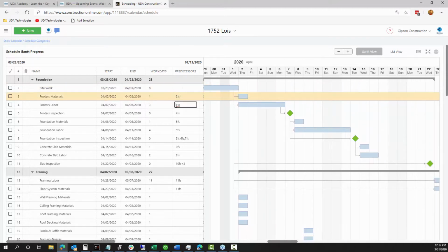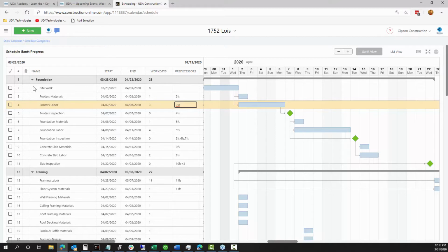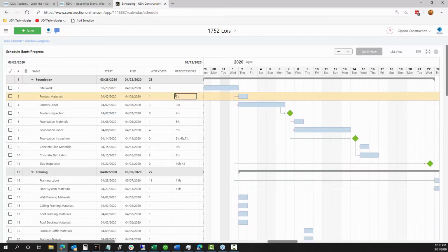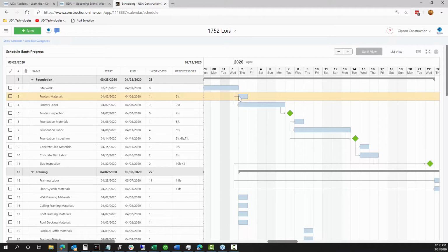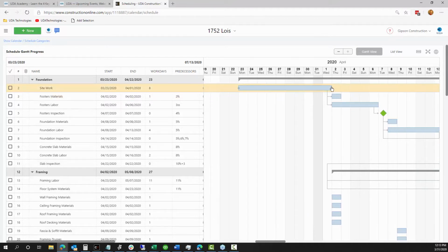So we start to see a chain of events happening here where if task number 2 is updated, well, we see that task number 3 is looking at task number 2 to find out when it should start, right? If we look at task number 4, well, the same is true for it. It's looking back to, or dependent on, task number 3. And really this starts to build a very powerful system in the schedule itself that can keep everything up to date down the line or at later parts of the schedule, simply by updating our earlier tasks and saying, well, it turns out that we had a couple of rain delay days, and we're behind by about a day. Well, that updates the rest of the schedule in series without having to go through and update every single event on the schedule.